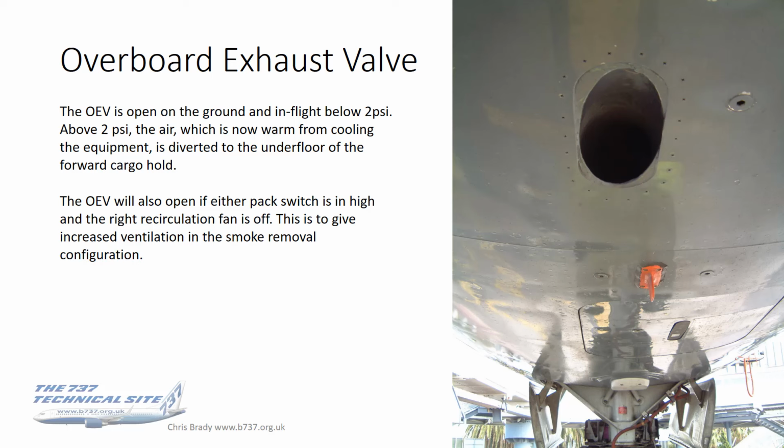The overboard exhaust valve will also open if either pack switch is in high and the right recirc fan's off, and this is to give an increased ventilation and smoke removal configuration.